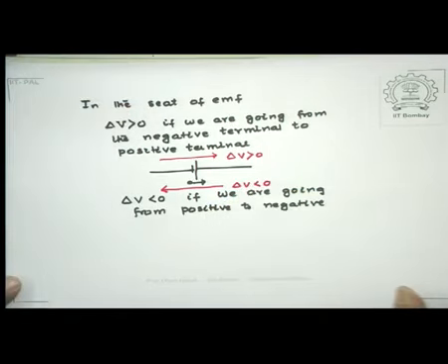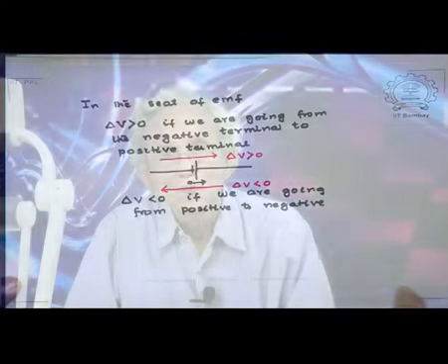Now, you do not have to know a priori the direction in which the current is flowing. You are allowed to make any assumption regarding its direction, and at the end of the calculation, if the numbers turn out to be negative, then you know that your original assumption was wrong and the direction of current should have been opposite to what you assumed.